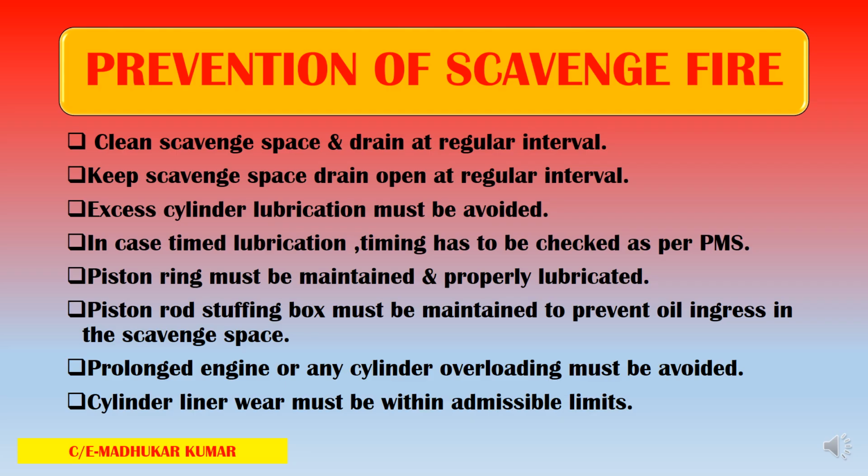Once you open the drain, you feel the drain pipe. If it is becoming hot, that means the scavenge drains are going down and the pipe is clear. So the flow is okay, no problem at all. Excess cylinder lubrication must be avoided. Yes. Less lubrication is also a problem.